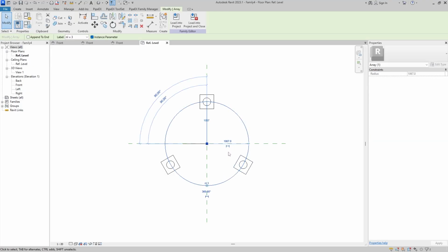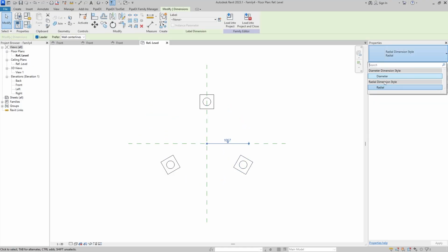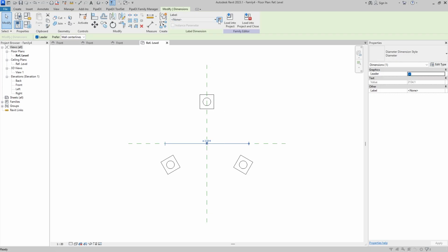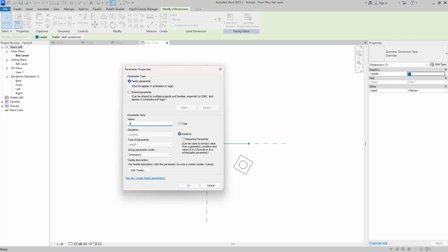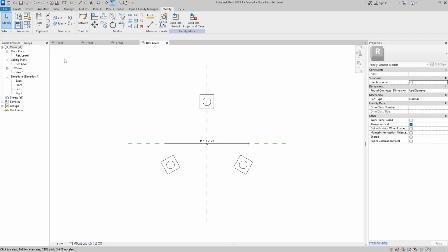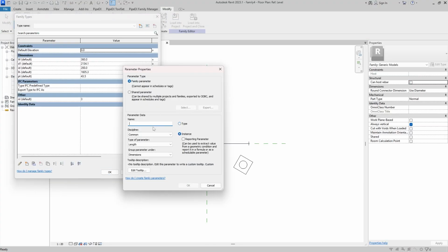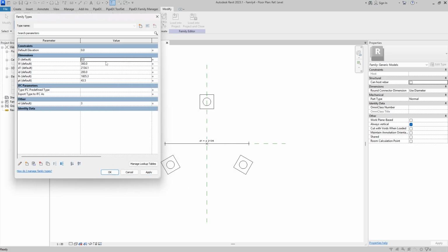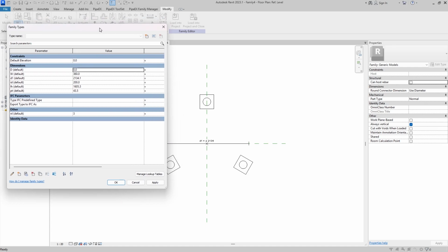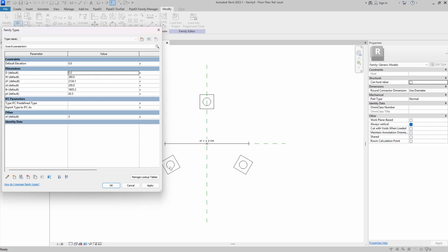And one extra parameter will be how those legs should be placed. So I will call this parameter d1, and here I'm going to define a separate parameter d that will be equal to the diameter of the tank. What I would like to achieve here is to ensure the geometry of the legs that I'm going to create will not go beyond the shape of the tank we are going to model.